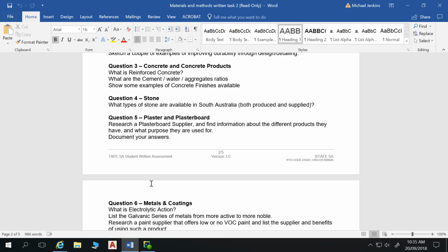Oh, definitely. Yeah. So the engineer is going to specify how that concrete is made, and then your concrete supplier and the people laying your concrete are going to work fairly closely together to ensure that that concrete is right. You'll want to achieve really thorough coverage of all your reinforcing, and you'll want all of that concrete to fill those sections clear, because you're going to strip away those form boards and you're going to see that wall, aren't you? Oh no, that's brick. Oh, that's right. Oh yeah, core fill. Sorry.